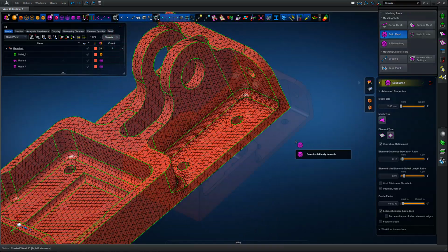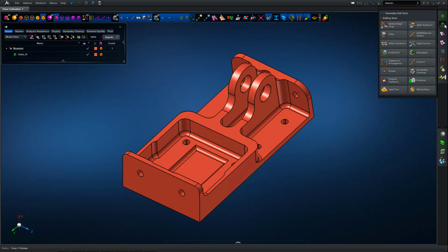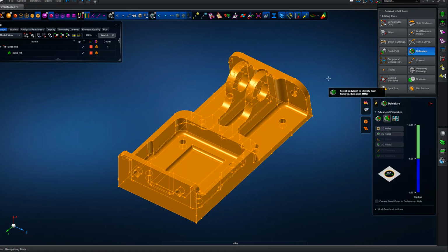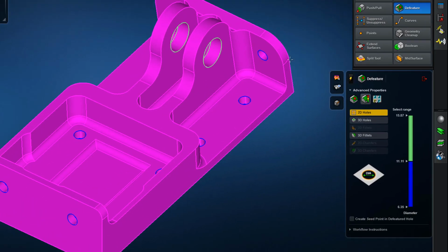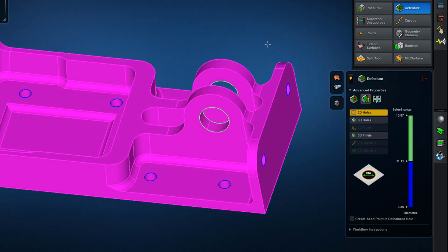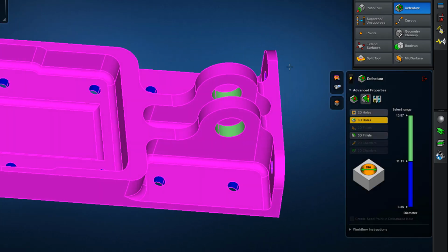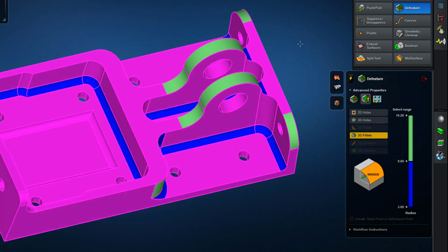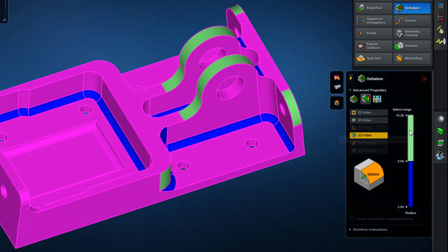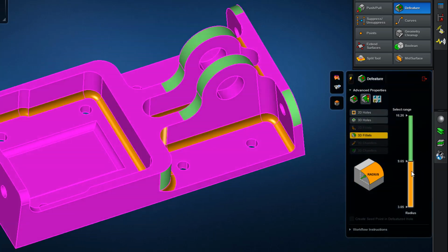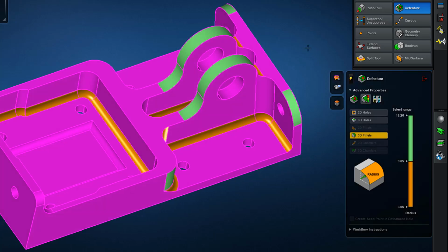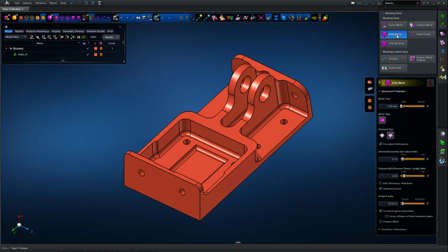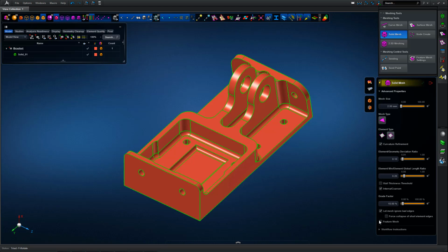Okay, so that would work nicely for lots of structures, but obviously if you've got lots of fillet detail, chamfers, holes, that type of thing, then you may find a lot of work is required in defining those 2D surface meshes in the first instance. So Apex has a different tool that we can use, feature recognition. What we're doing first of all is highlighting, using the standard geometry defeature tools, some typical dimensions for features that we might be interested in. So we can see here we've highlighted all the smaller fillets in the model, and we can measure those accordingly to drive the feature mesh settings that we'll come on to in a moment.